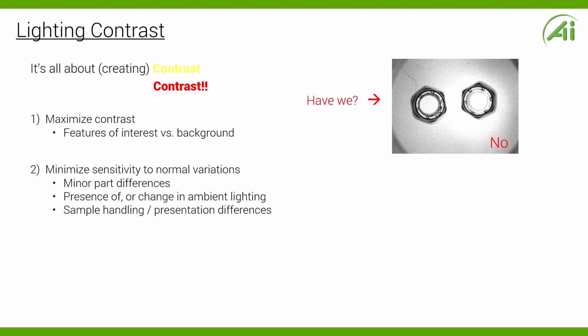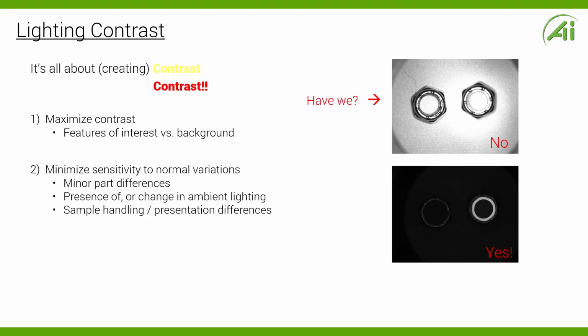So how do we change that? Well, the obvious solution in this situation was that knowing that when you fluoresce the nylon with UV light, it tends to emit a blue wavelength. And so it's easy to isolate that wavelength using a pass filter. The bottom line is then by just simply adding this pass filter into the optical path, we change the contrast remarkably. So you want to remember that although point 1 may solve some applications, you want to always keep in mind number 2 can be critical as well.